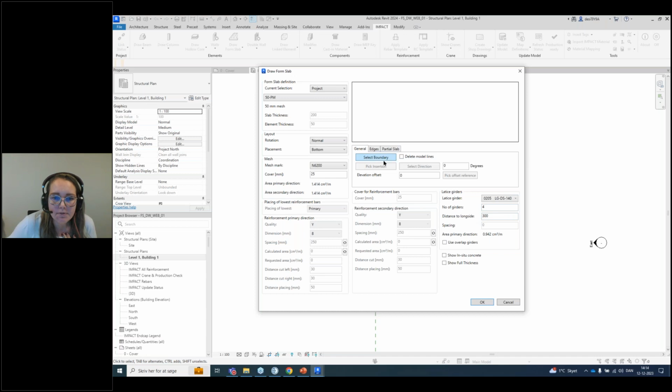Now, if you want to draw, there are 5 ways to do it. You can pick a structural floor, if you have that, let's say it's a Revit model you have. My personal favorite is pick model lines, which I think gives a lot of control over your design.